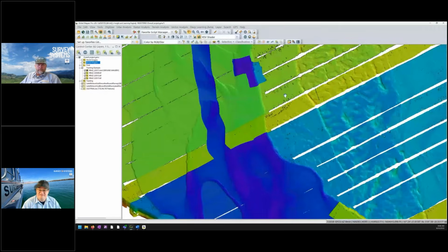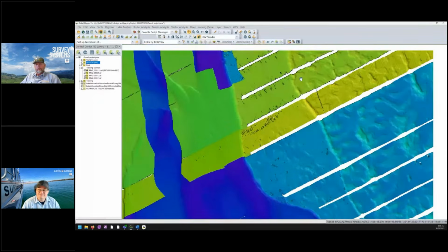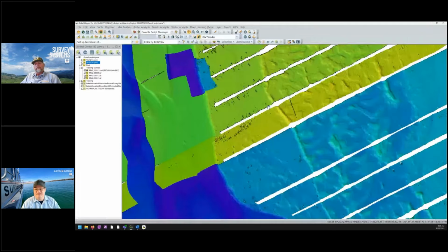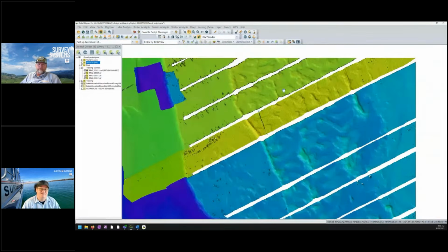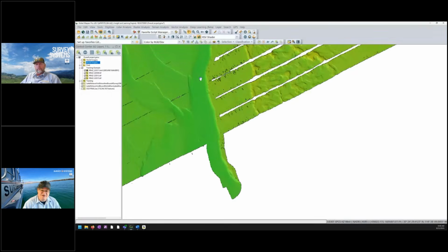This data wasn't cleaned. It's hardly been processed. It was just brought in. It's just looking at where we've been and whether things look out of place. Like I have a line here that looked a little bit rougher than the other lines. So that was a line that I sent back to the crew in the field and said, hey, next time you're driving through here, we can grab that line again because it just doesn't look the same as all the others. And we'd also identify features, as in the tops and toes of a channel.